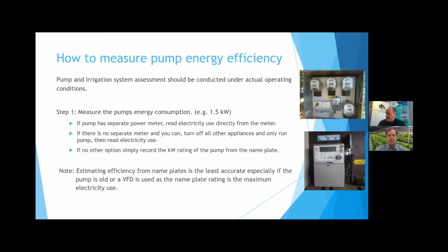So just while we're there, David, I've got an example from a few years ago. We had a pump assessment on a bore pump, and during the course of doing that, they didn't know what was down the bottom of the borehole, what size motor there was on it, what size pump, and I measured the energy from their electricity meter. When I went away and did some calculations, I worked out that there was no way that they could have a motor of that size down the bore. And as it turns out, about 2 weeks after I did the pump assessment, the motor on the bore pump blew up. So it was obviously on its way out, and it was using a lot more energy than it should have. So that's one of the dangers.